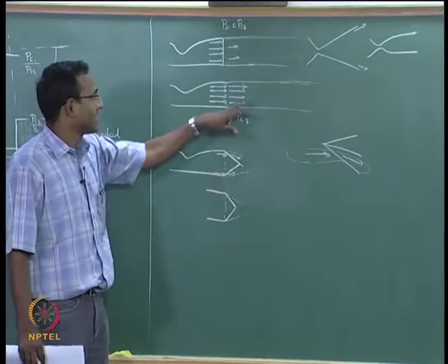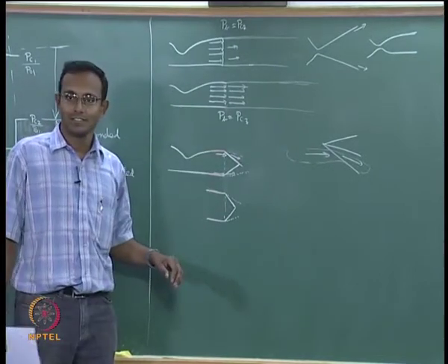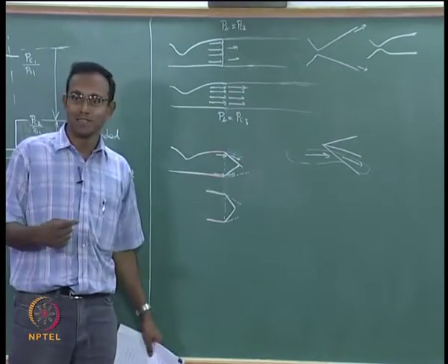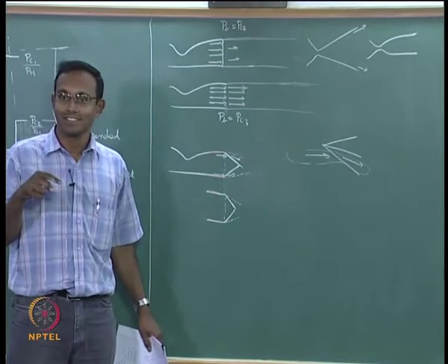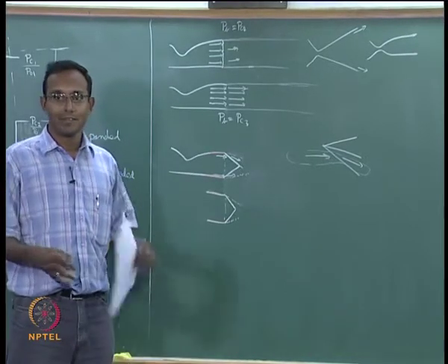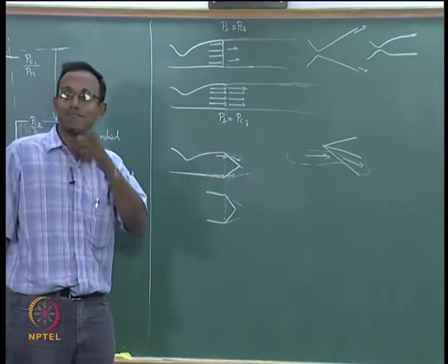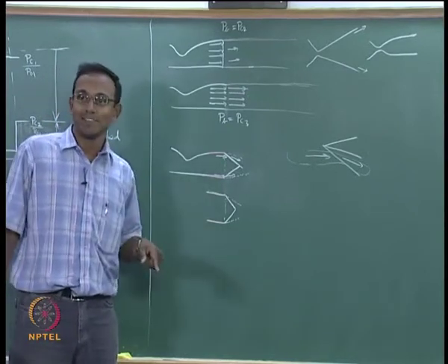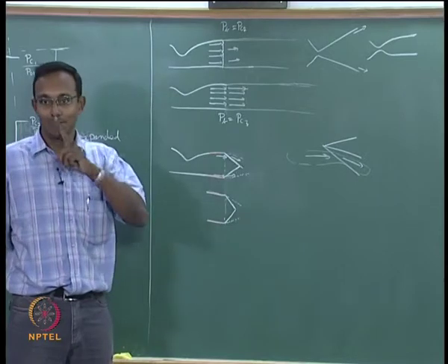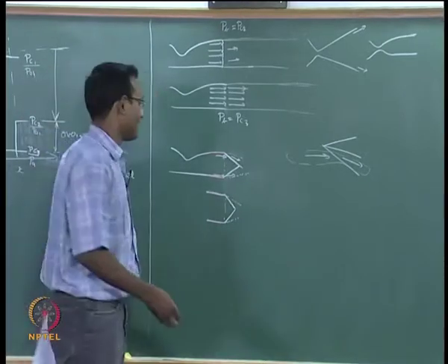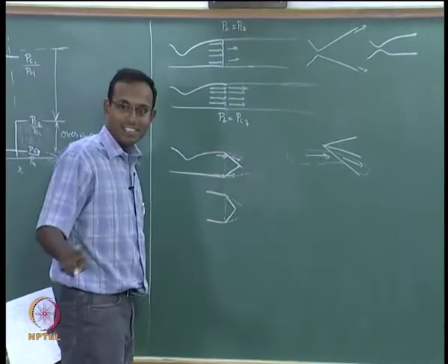When will it become this case? Do not talk about the PB now, tell me something about the beta. Beta will not become 90 degrees, beta will not become 0, that is why I asked this question. Beta will go to mu, the Mach angle, that is the weakest shock you can ever have, right. Beta will become mu, that is a specific reason why I asked this question.